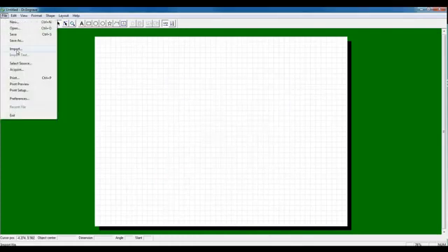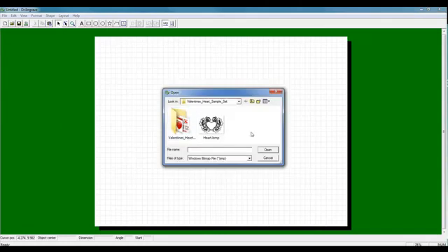Next we want to go ahead and import our graphic. DrEngrave only supports BMP and DXF formatted images for vectorization. So if you're working with a TIFF, JPEG, EPS, or AI file, you want to make sure you export or save as a .bmp before bringing it into DrEngrave.